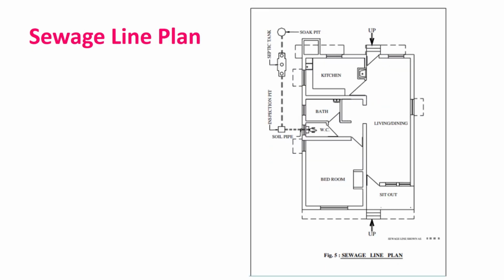Because there may be a case, possibly in a corporation, where you have a sewer passing near your plot and you want to connect your surface water drain to that. So please take the written approval of the authority. And please don't make such a storm water drain where we have some type of a structure in between and it doesn't serve the purpose.